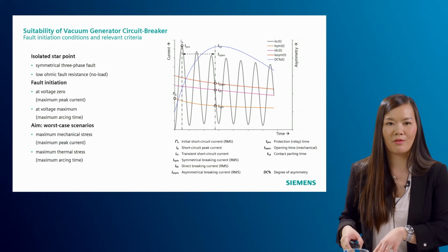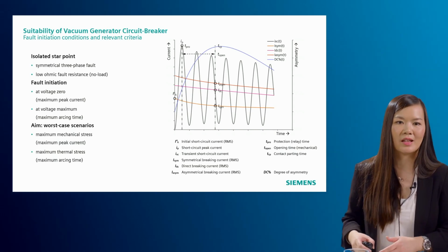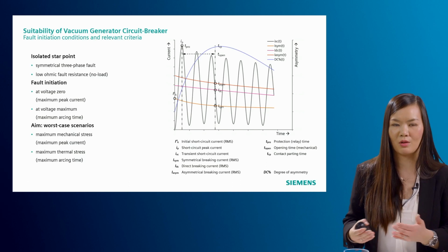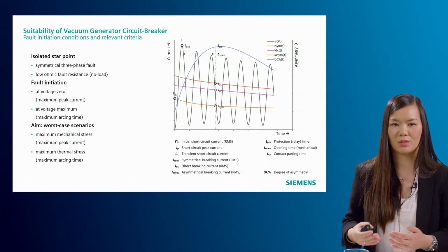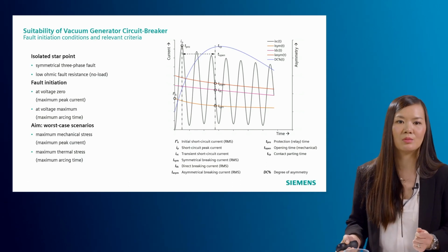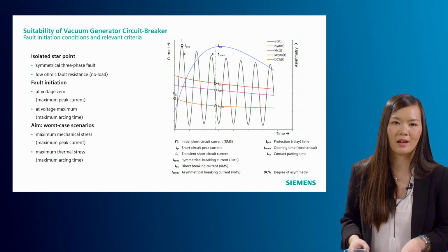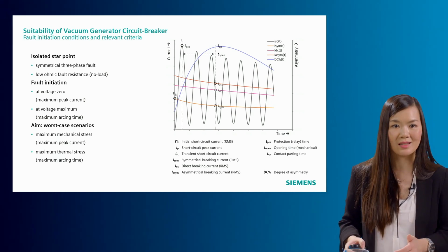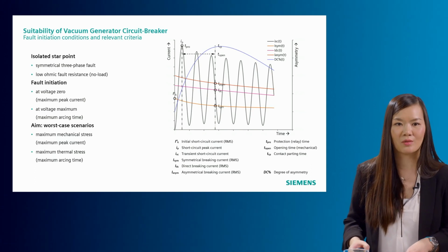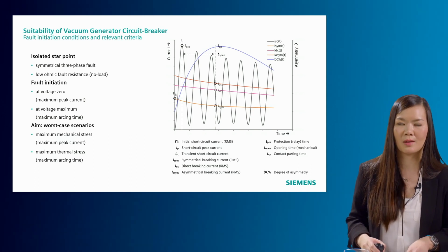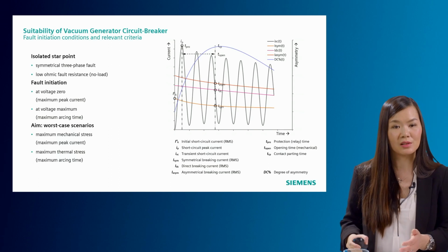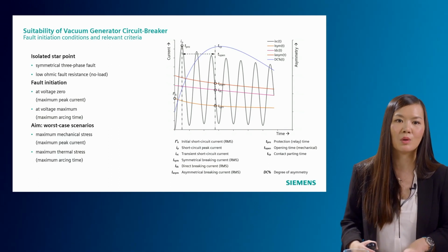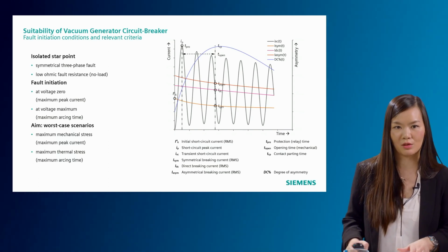When it comes to the generator already being in service, like in overexcited, underexcited, lagging and leading operating points, then you have to consider, of course, the arc voltage of the circuit breaker itself. And additionally, you also have to consider the arc fault with a minimum arc fault of 300 volts.